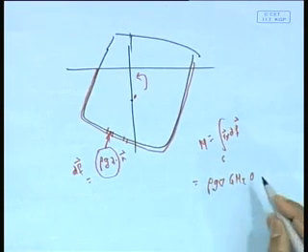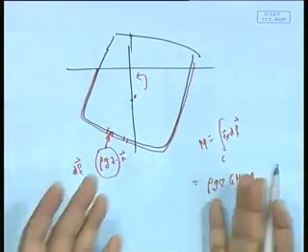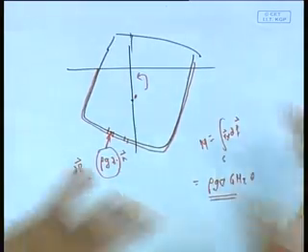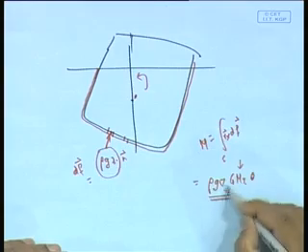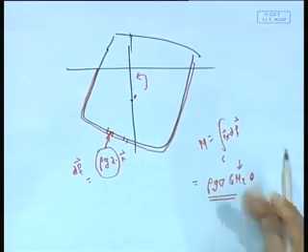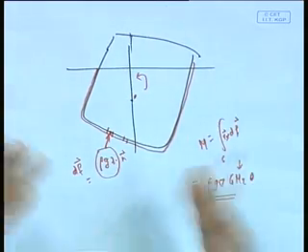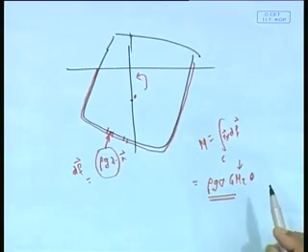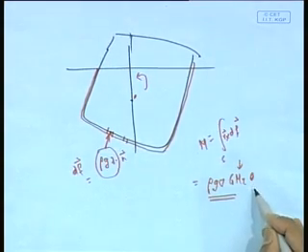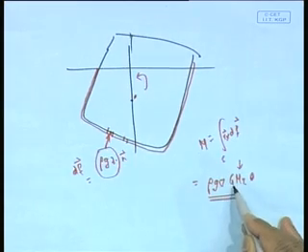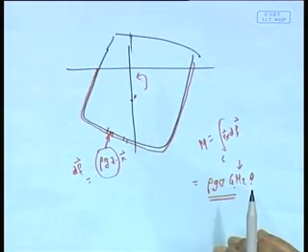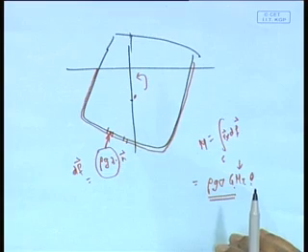The direction depends on the GM_T quantity, because the others are constant; rho g V has no sign attached and is not a directional quantity, and I am always taking theta positive. So if the moment is opposite to theta, it restores. This was the concept we used.